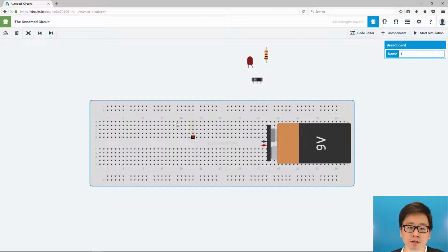And when you look on the breadboard, it splits into 3 sections. You have the top and bottom, with the plus and minus sign there. These are called the power strips, and these holes are connected in rows along the whole length of the board. That's obviously for the negative terminal, and this is for the positive terminal. And same again for the bottom.